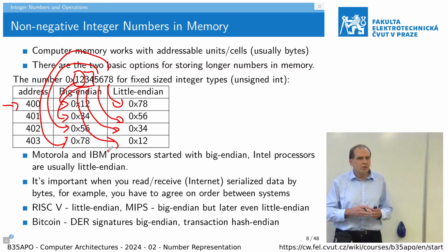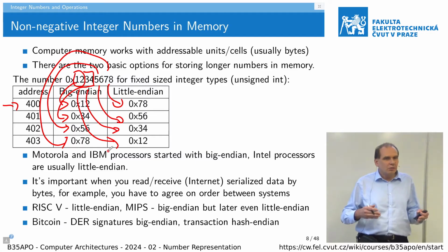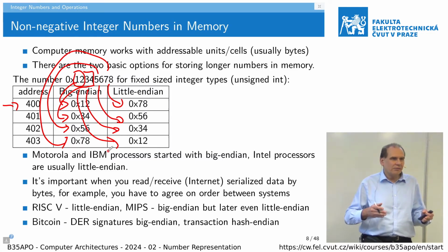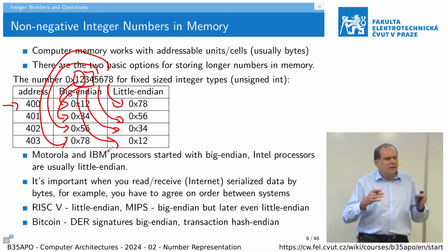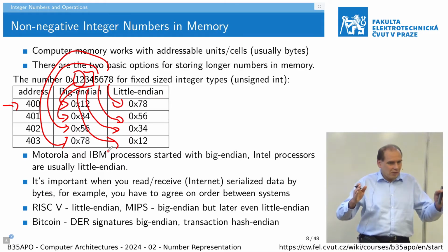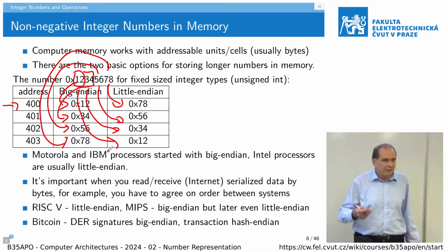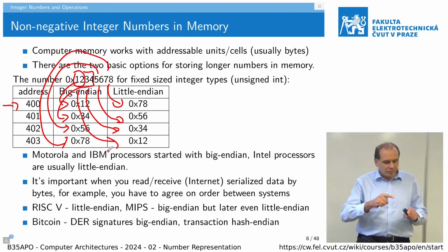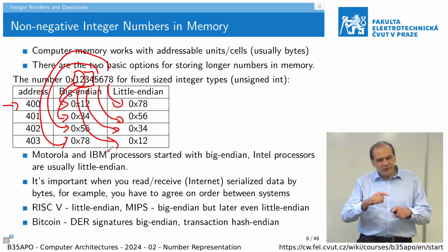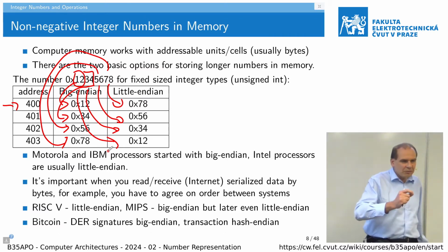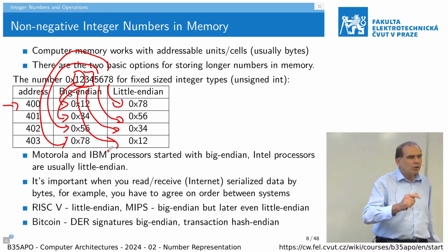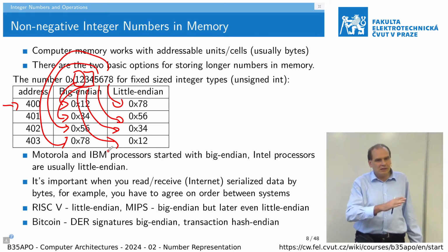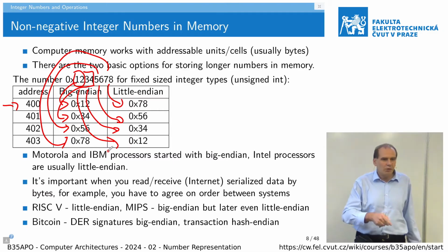If you need to compare 2 very large numbers, for example 256-bit numbers, you usually do not have instructions to compute this. And if you compare from the most significant bits to the least significant bits, then at the moment you find a difference, you know that you can stop, because one is bigger than the other and you do not need to compare further.